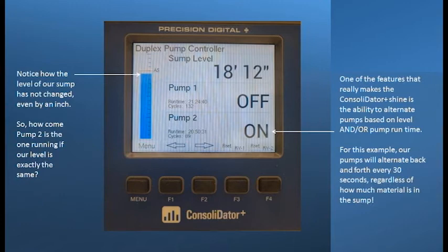And another question, can we use Modbus for the level readings? Aha. So the short answer is yes, we can use Modbus. The long answer is, well, we have a class on that in a few weeks. So we'll hold off on the Modbus talk for now. But yes, we can use Modbus. To keep it short and simple, we can be used on Modbus RTU as a master, and we can also be used as a slave. And then on the Ethernet side of things, we can actually do Modbus TCP/IP using Ethernet, and that would be used as a Modbus server, as they call it now, if we change the nomenclature.